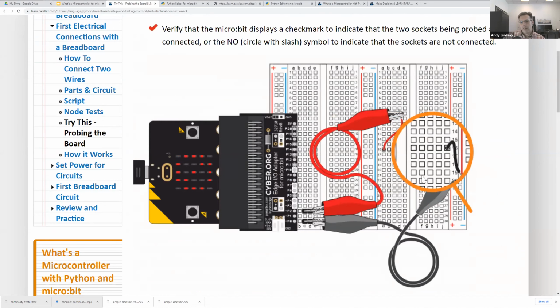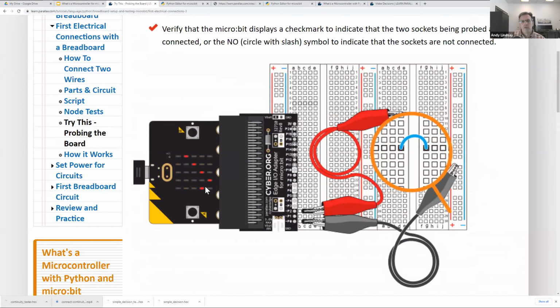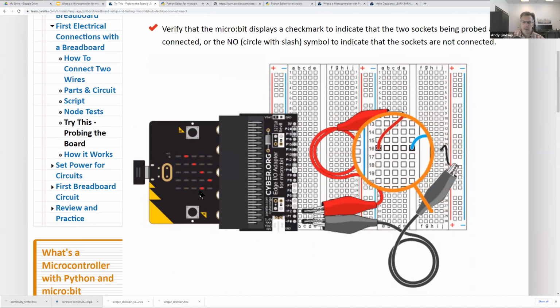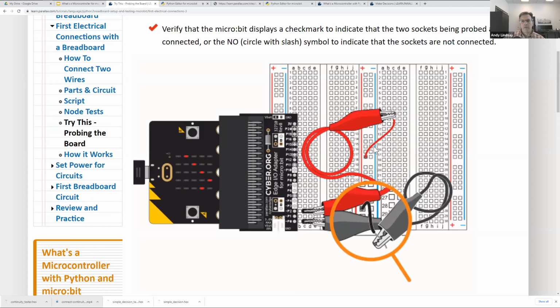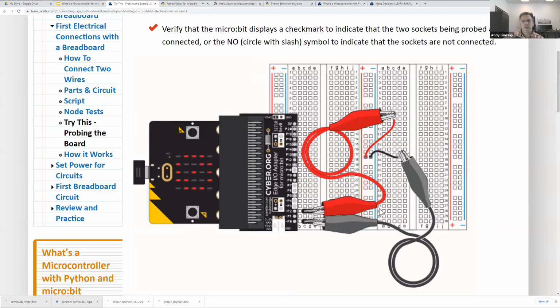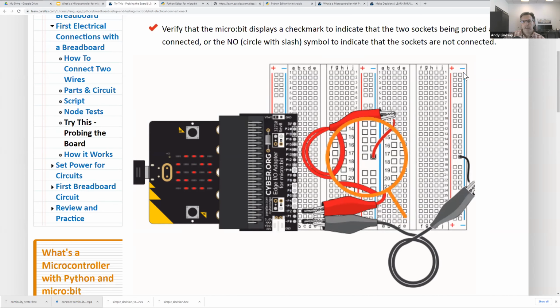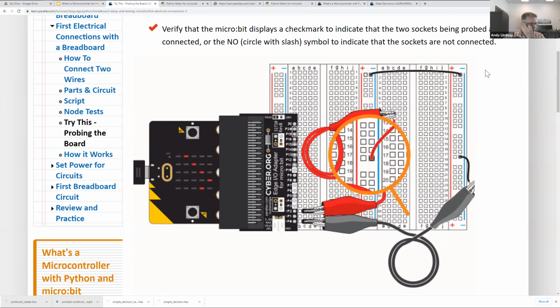And the blue wire, incidentally, comes into play when you want to connect these 2 rows together to see that you are connected. And we also do the column tests. And that's where the second black wire comes in, because the second black wire is going to jump 1 negative column, 1 blue line negative column to the other right there to verify that it's connected.